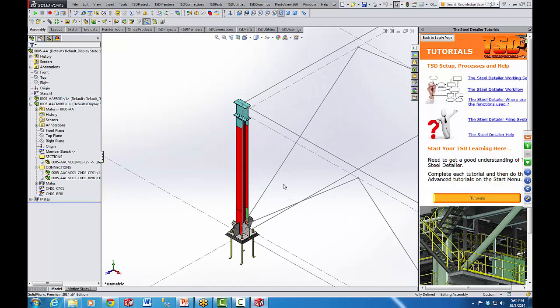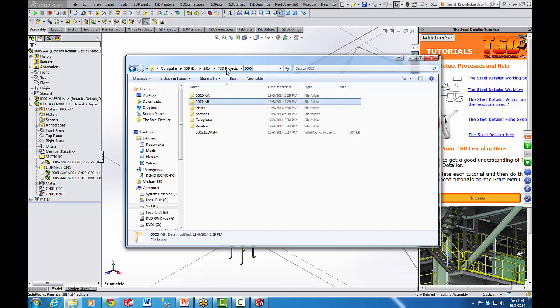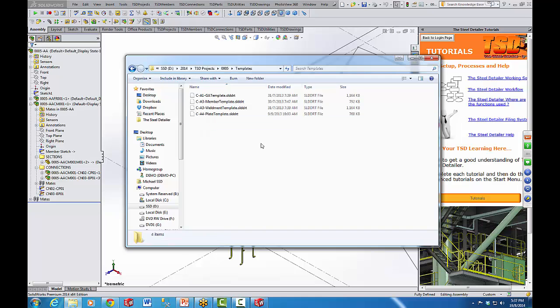Okay, so let's have a look at the templates and see what we can do to get those to work a little bit better than what we already have. If we go into the actual project location, let's check out the templates. And this is where we're getting an issue. Sorry, it's this weldment template. That's the one where we're getting an issue, where it's come in as an A1 rather than A3. So I'm just going to change that so that it is now going to be A3.